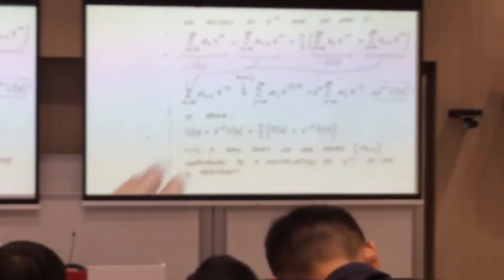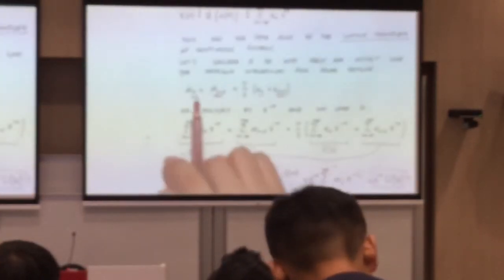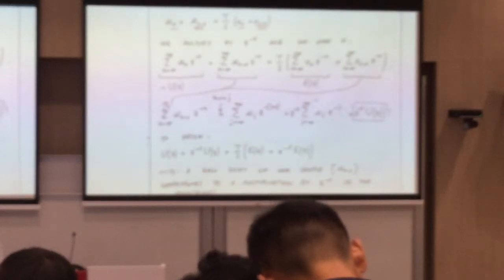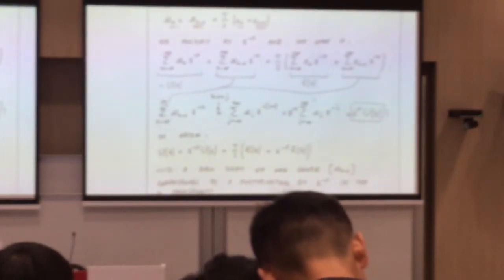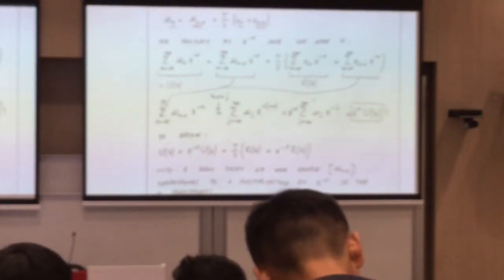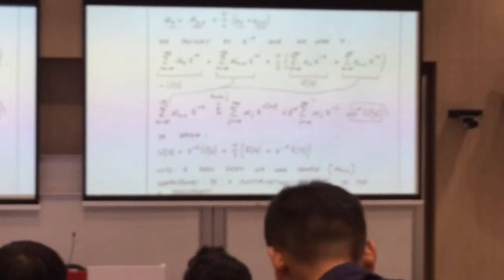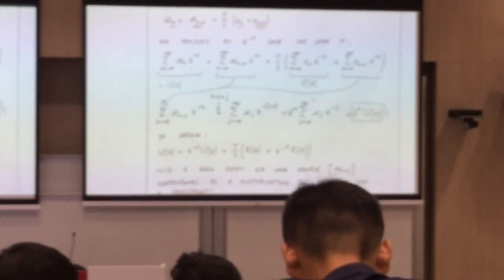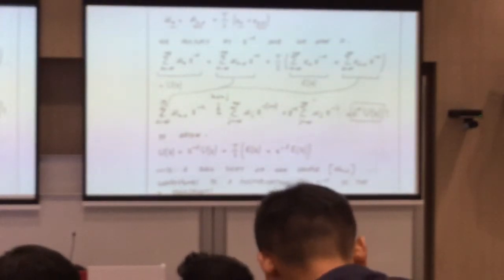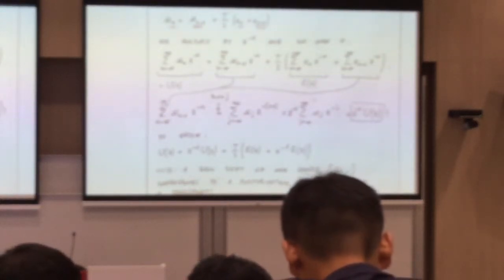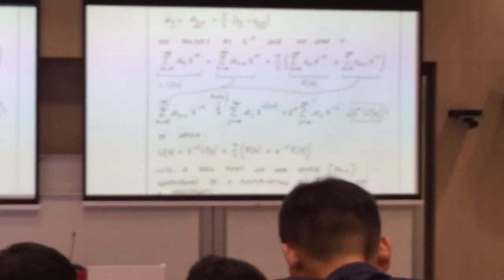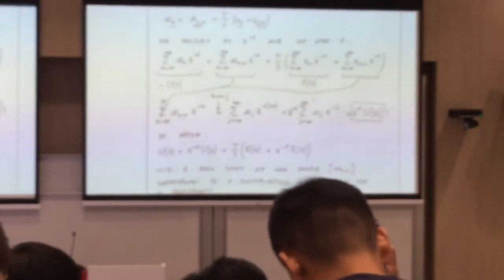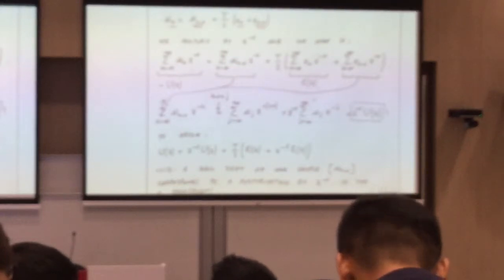So after you have done the Z transform, you only get one variable, but all the time delays become Z power minus 1, Z power minus 2, Z power minus 3. Then you can obtain a polynomial function with only one variable Z. Now think about the Laplace transform. You got first order, second order, third order, fourth order, fifth order, nth order. After the Laplace transform, you don't have that many orders of differential equation, but you get a certain order of polynomial function.